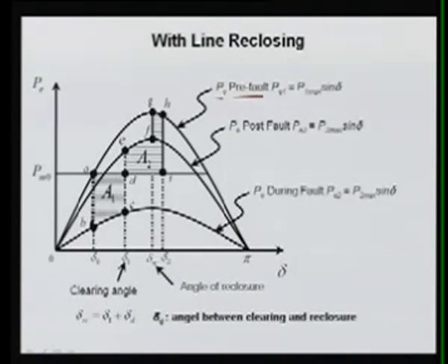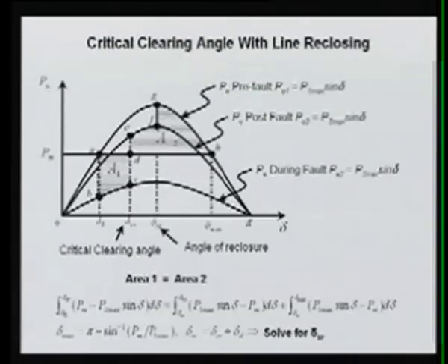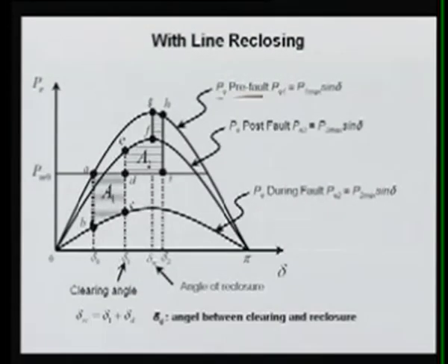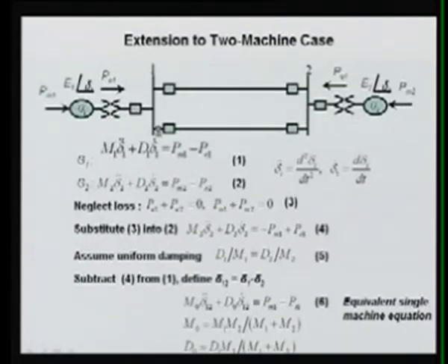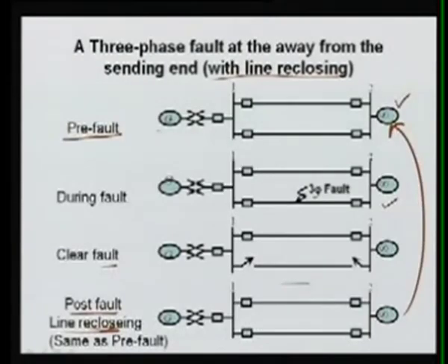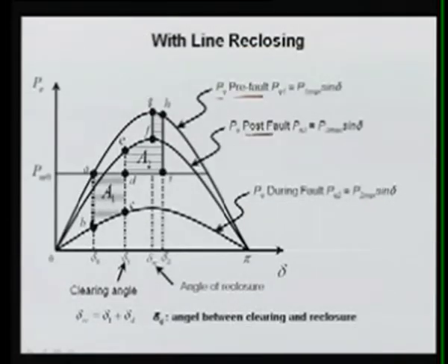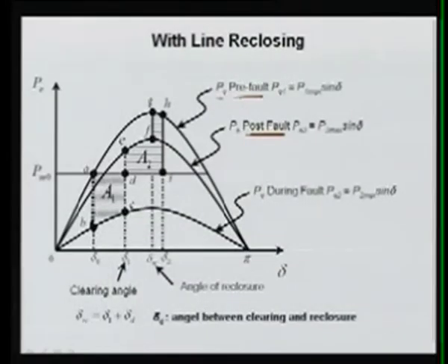The fault which has occurred here, you can see this impedance is the same; here the line is cleared, so this is a fault clear. This impedance is just like the previous case post-fault. This curve is basically the fault cleared. At that time the fault is clear, but it is not post-fault. Post-fault is again this condition, where it follows the same PE.